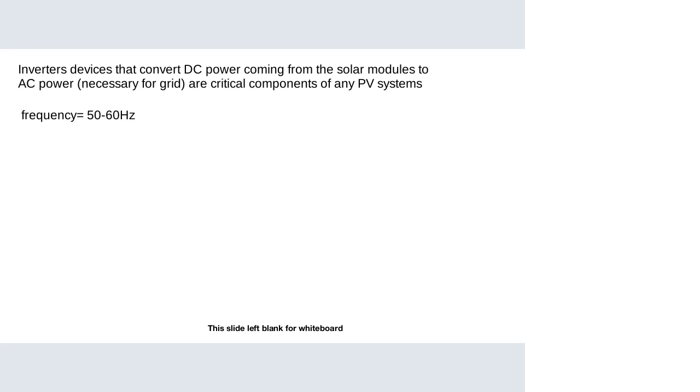As with all power system components, the use of inverters results in energy losses due to interferences. As we all know, every electrical component comes with its own losses. So when you apply an inverter in your PV system, it brings about energy losses, due to the interferences. Typical efficiency of an inverter that is well matched to the array is around 90%. That is a very high efficiency.